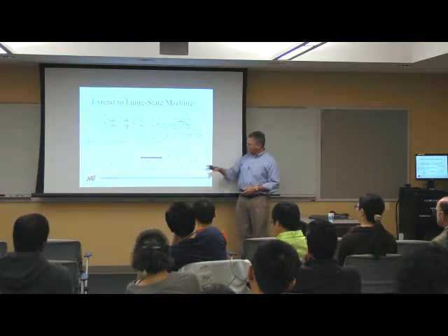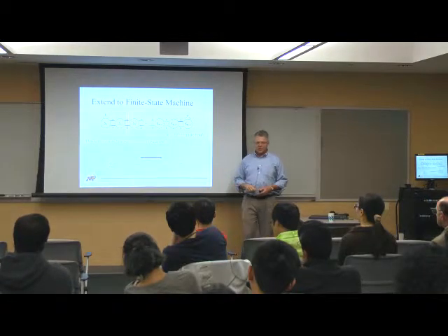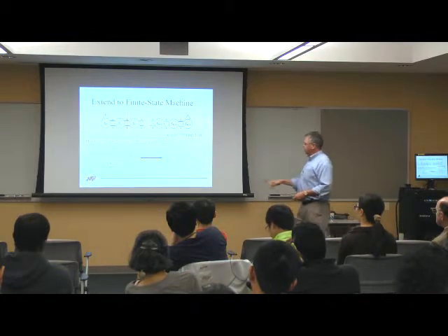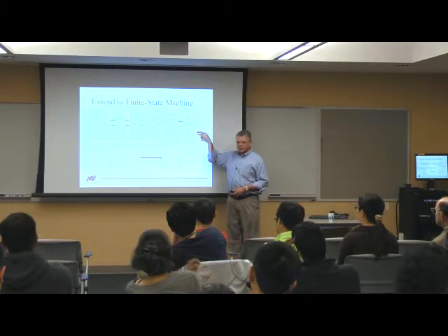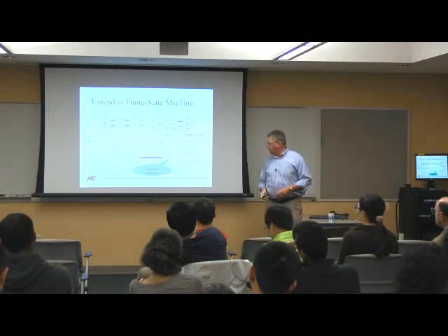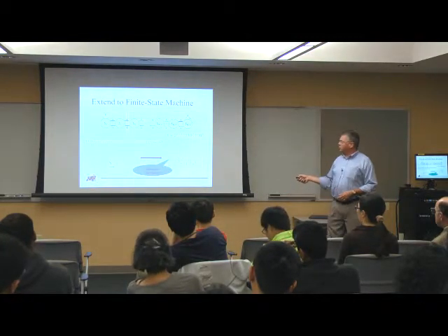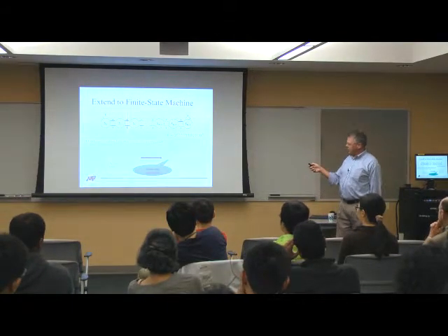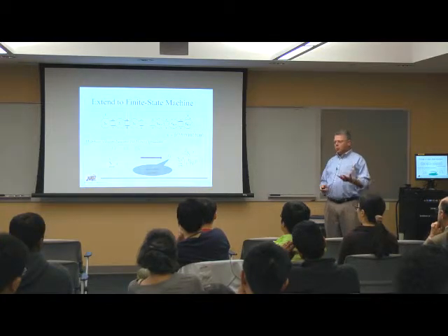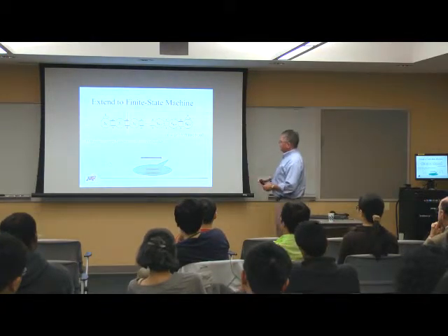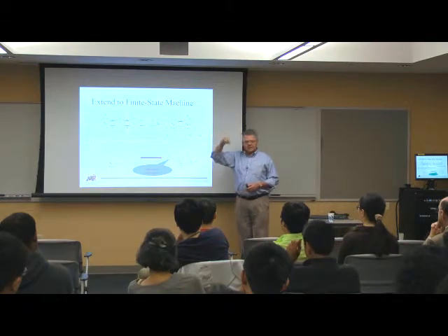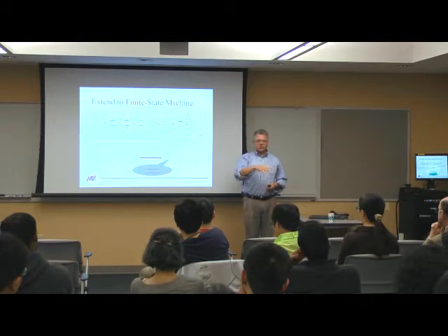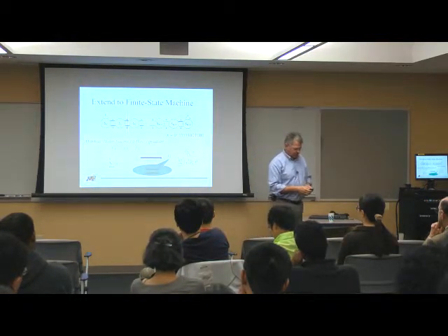Okay? So now my basis function is p of x over 1 minus p of x, where p of x is the probability of the input stream, the probability of any one of those bits being a 1. So I now have this stationary distribution for this finite state machine. Given this stationary distribution, I can come up with a variety of different functions simply by choosing which of the states I select to be 1. Set some of those states to 1, some to 0. If they're 1, that's my output.